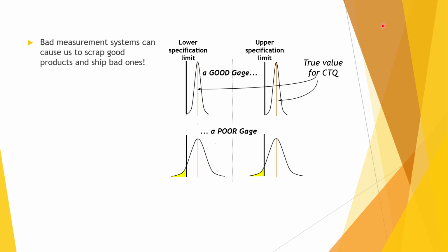And then you also have a go/no-go gauge. This measures manufactured items and determines whether it meets dimensional tolerances. It is an attribute gauge because a part is rated as good or bad, pass or fail. It is commonly used in production because measurements can be made very quickly.